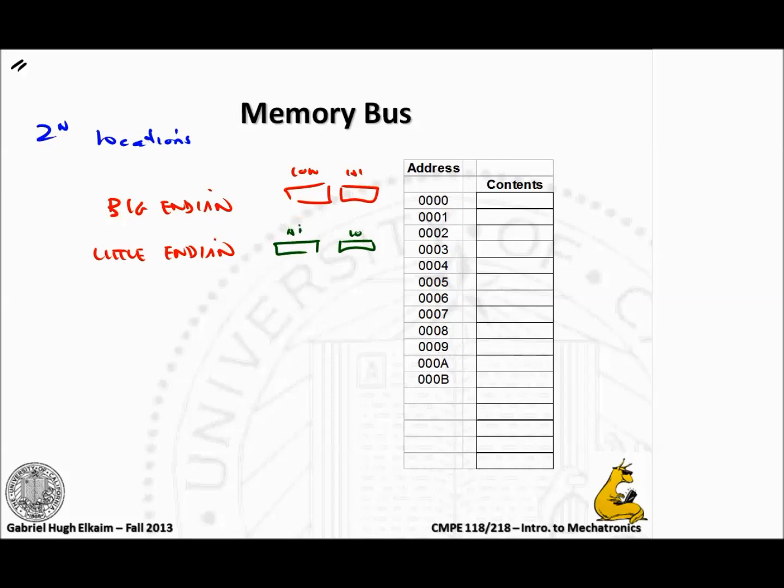Now, what's really interesting about this is, the same is true whether you're using floats, which are 8 bytes put together. They'll be in backwards order from one to the other. And for some reason, almost all microcontrollers are one kind, and almost all desktops are the other, which means when you do communication between the two, you've got to swap the bytes every time, which is really annoying.